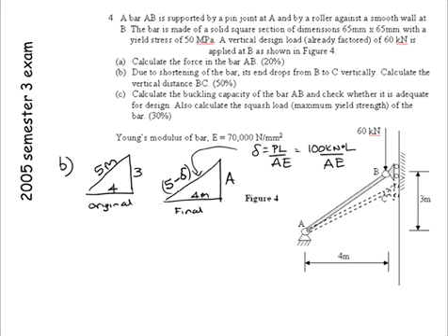Now I'm writing 5 minus delta. You need to get your units correct. If you choose to work in millimetres here, realise it would be 5,000 minus delta. Okay, but anyway, based on Pythagoras, A here is equal to, 5 minus delta all squared minus 4 squared.